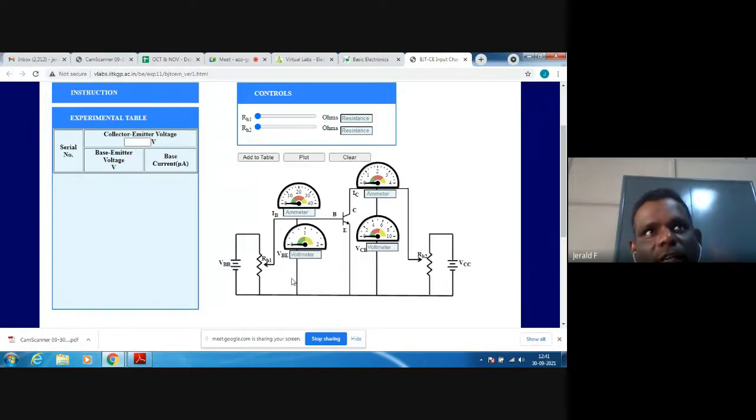Suppose we have the first 3 rings. What is the first ring? That is called brown. What is the brown value? 1. Black is 0. And red is 2, so you can add 2 zeros. 1K. So what is the fourth ring?